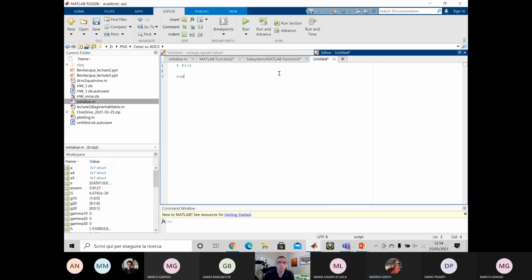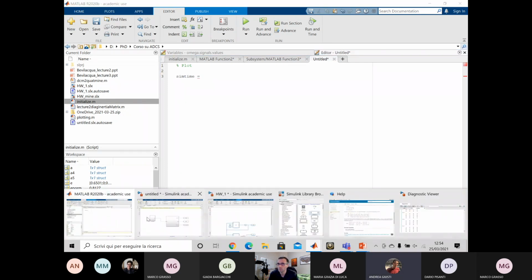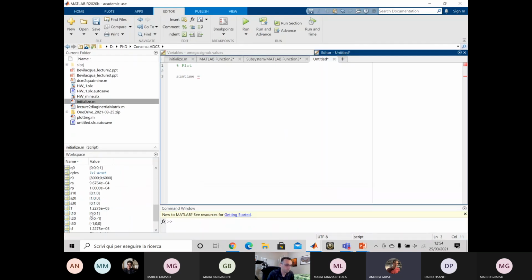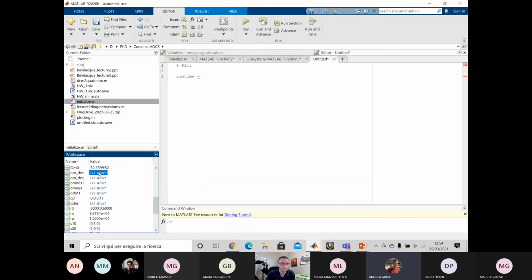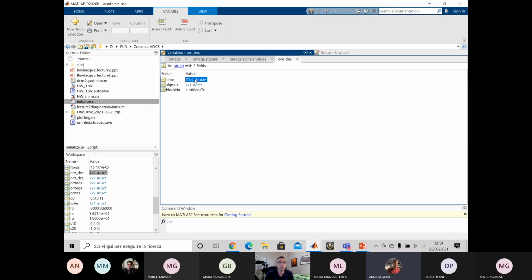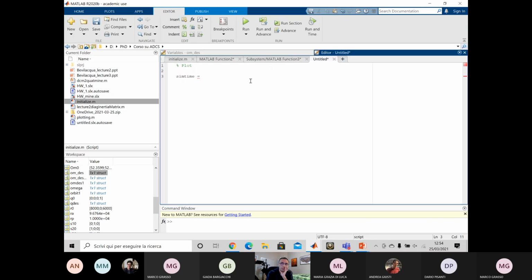Correct. Okay. So we will then put in something that closes the feedback between the desired omega and the torque. Yes, and as I just said, the Euler's equations block will be replaced by something quite a bit more complicated, because we will have generally variable speed control moment gyros.